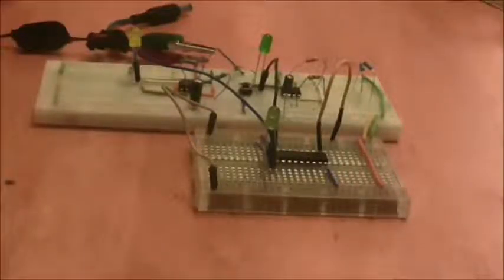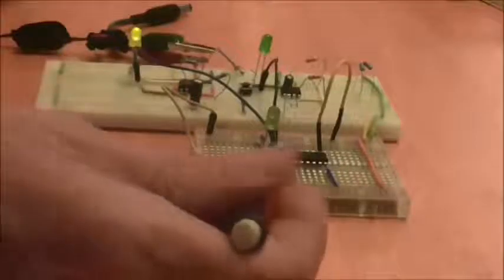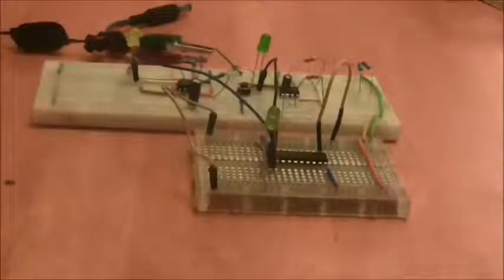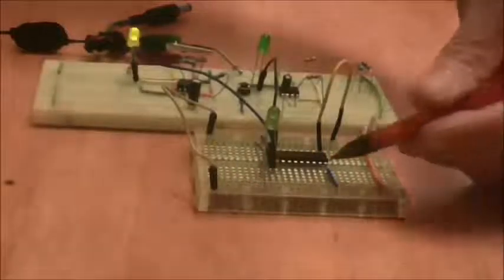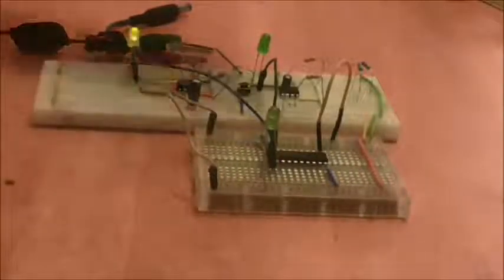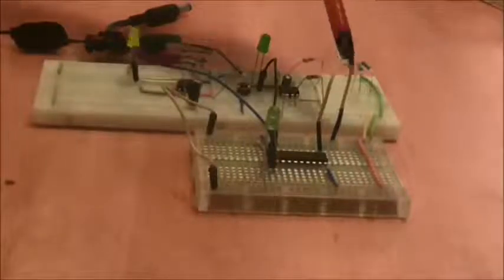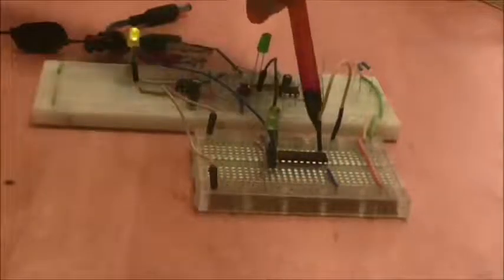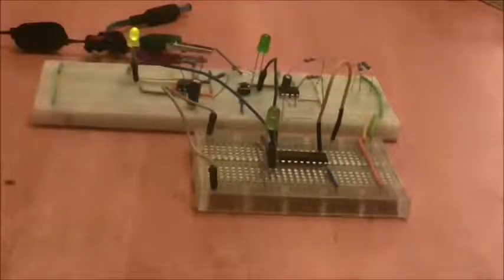So we're going to complete our video here by coming back round to where we started really, and that's with a flip-flop, and that's what this big 20-pin chip here is. This is an SN74HC574 and it's a D-type flip-flop. And so, we feed it power, positive there, ground there, and like the shift register it has a latch, and we keep this latch low all the time. And by keeping the latch low we can make it transparent data through.